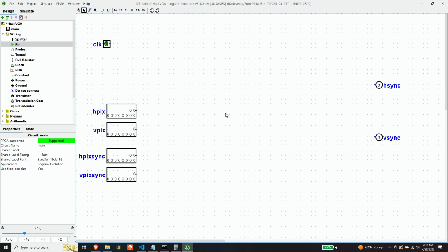And to make this totally generic, if you watch the intro video, you'll remember I talked about sync polarity. There are different standards that define the polarity of each one of these. We're going to be using the CVT standard. If you really wanted to make this generic, you would have some flags that tell it which polarity you want. And that's what I want to do. It makes it a little more complicated, but I like to have this thing totally generic because I'm going to be using it myself for maybe other purposes, other videos, etc.